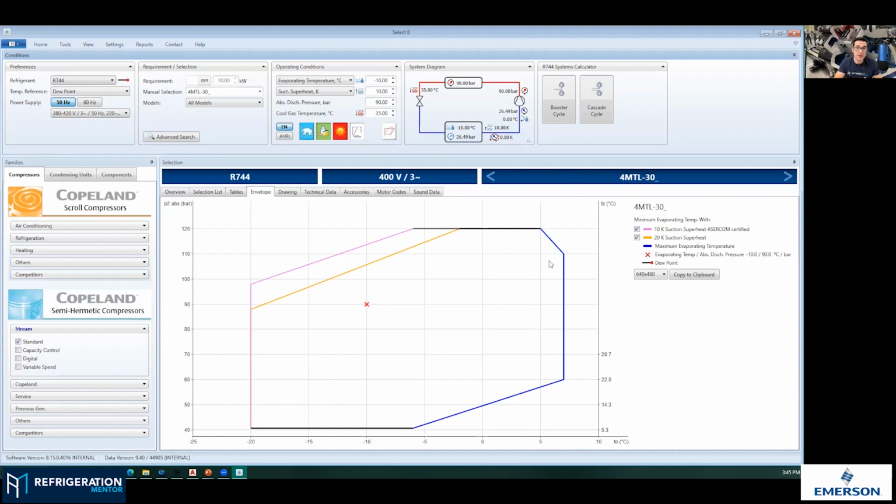It's not only the temperature that could trip the motor or the compressor, it's also the amp. So you really should understand which one it is and what caused it. Because looking inside the compressor will tell you, especially if it failed, if you had a lot of overheating, right?